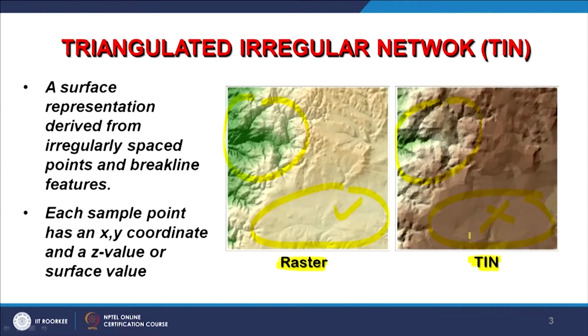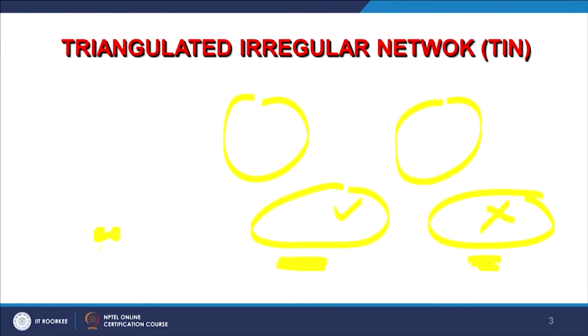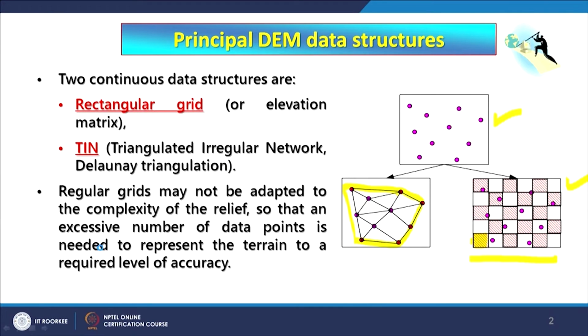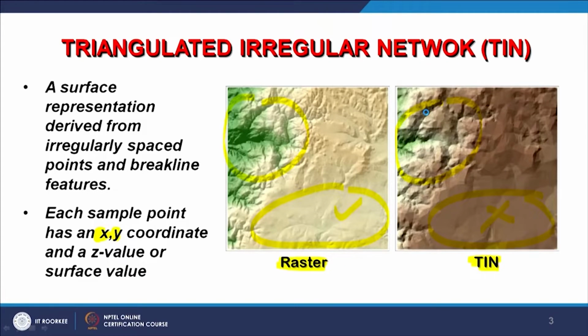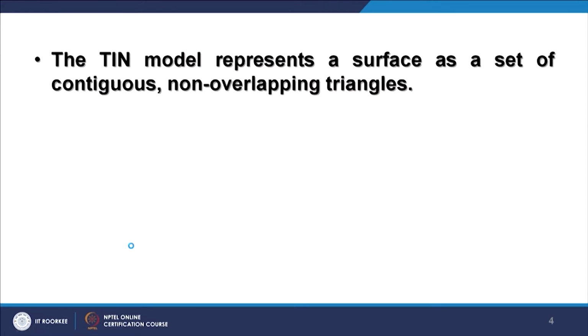Of course, here also when we provide the data for generation of TIN, three things are very much essential. One is the x coordinate, and the y coordinate, so it is a pair, maybe many points. Like here when I was showing that these are the points, and for these points one more value you have to provide, and that is the elevation value, the Z value. So, the Z value is also provided here to create the surface, whether TIN or raster.